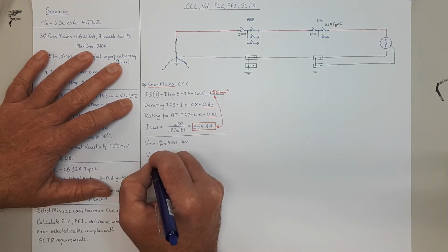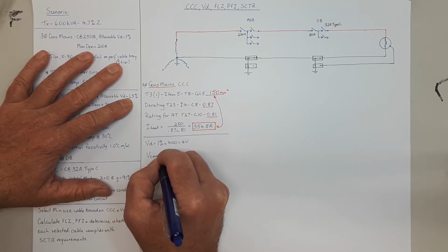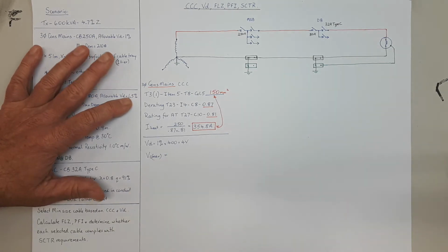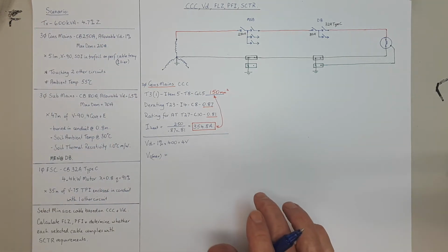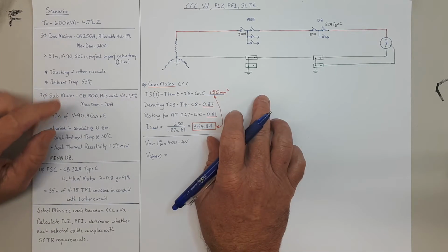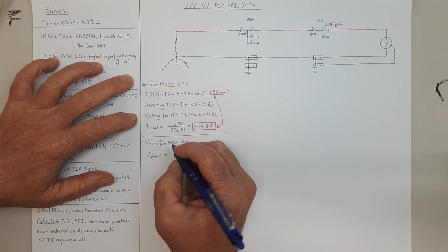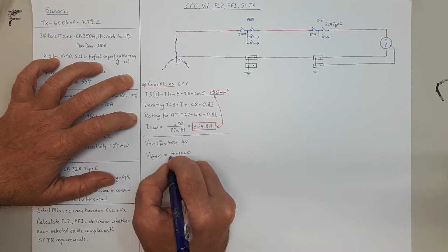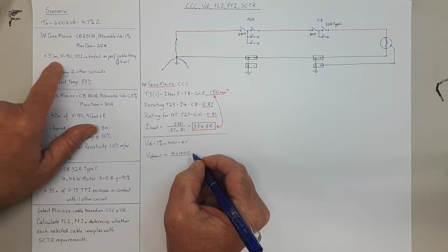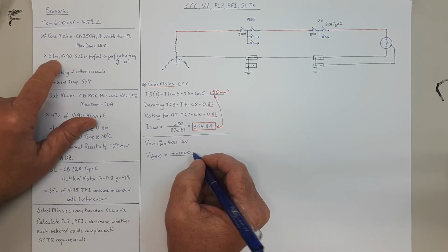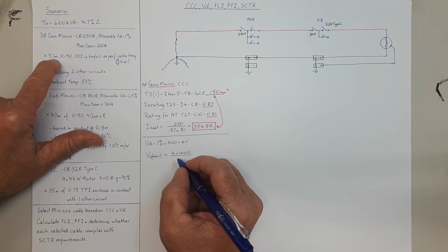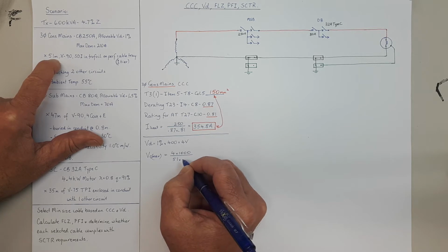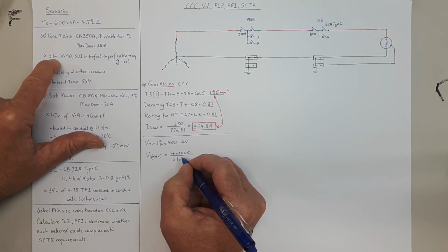So then we're going to look for what's the maximum VC we can use. Now VC is the voltage drop in the cable in millivolts per ampere meter. And that, as it turns out, we work out by 4 times 1,000 over length. It says the length there is 51 meters. 51 times 210.